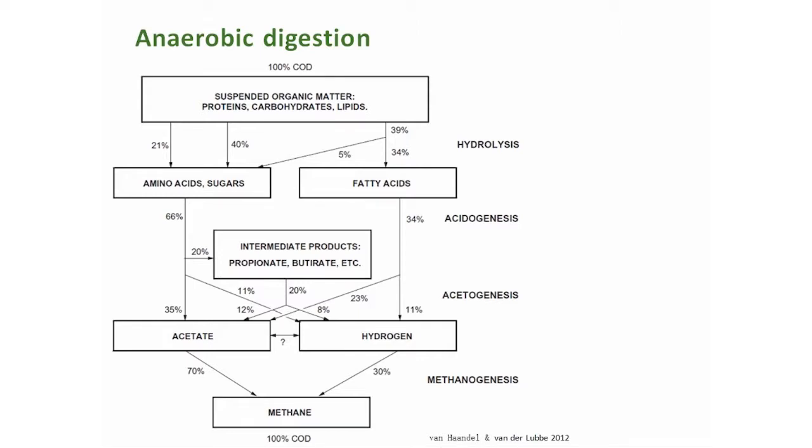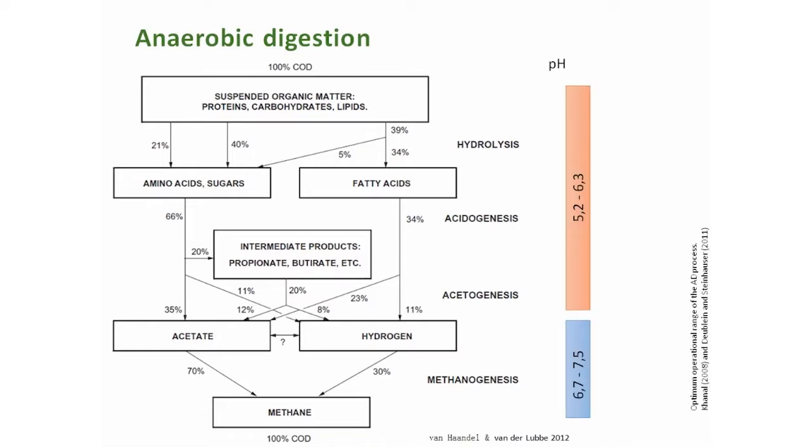After the acidogenesis, everything which goes over acetate is mainly by archaea, going over to form methane. Hydrogen is also produced as a byproduct or intermediate product, and hydrogenotrophic microorganisms form methane finally. So there is also hydrogen gas produced in the same type of process.